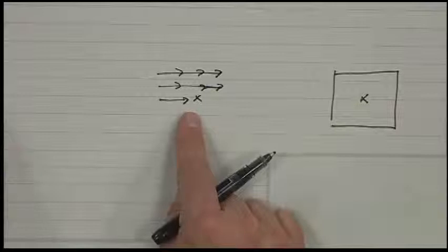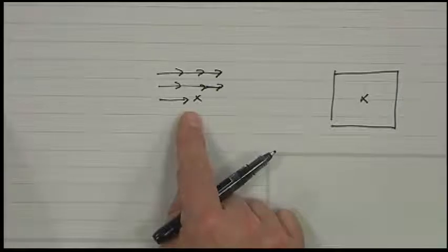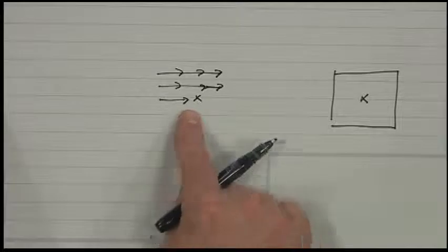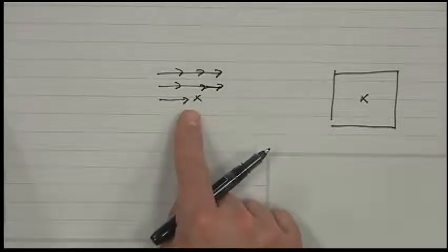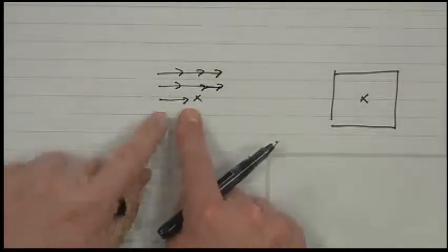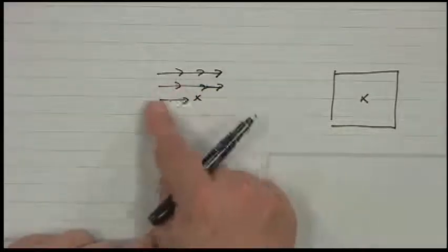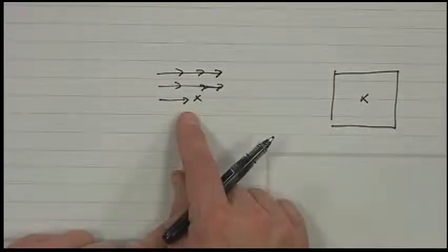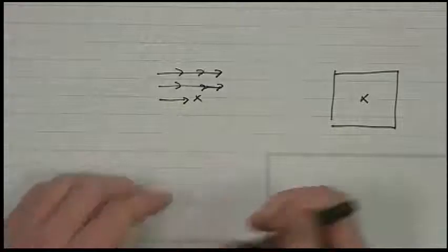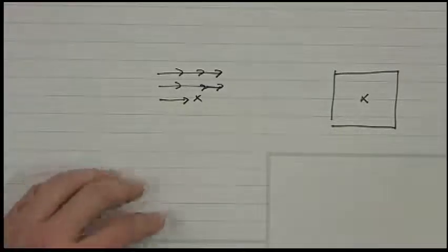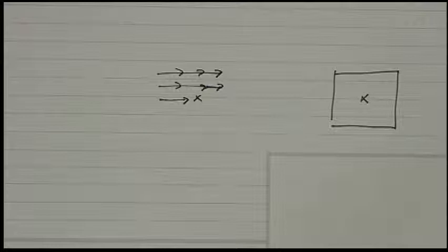The upside of the IIR filter is that it can have much lower complexity to implement. But the downside is, first of all, that the design problem is more difficult because it's a nonlinear design problem. Second of all, the response of the filter inherits the intrinsic anisotropic behavior of the raster ordering. So inevitably, not always, but often, that tends to produce problems that have to be fixed.